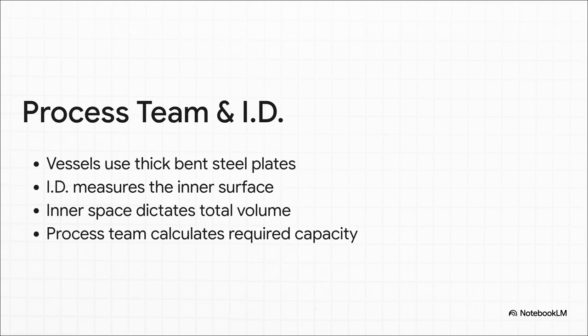And who cares the most about volume? The process team. They're the ones calculating exactly how much fluid or gas needs to be contained, heated, or separated for the plant to actually work. Therefore, the process team dictates the ID to ensure the vessel physically holds the required capacity.